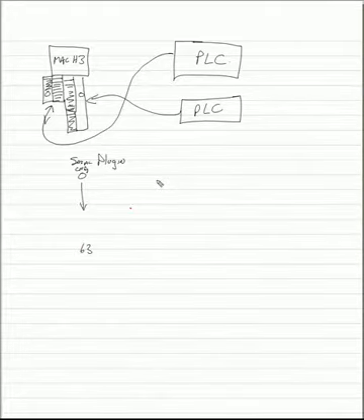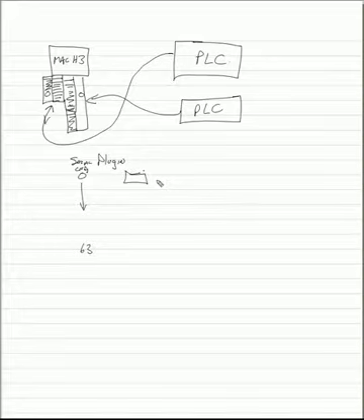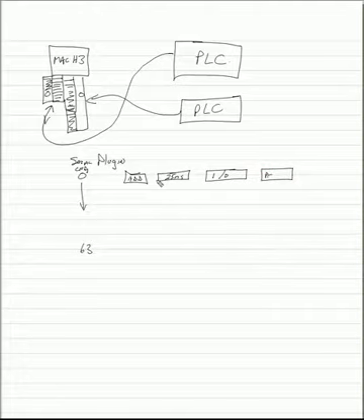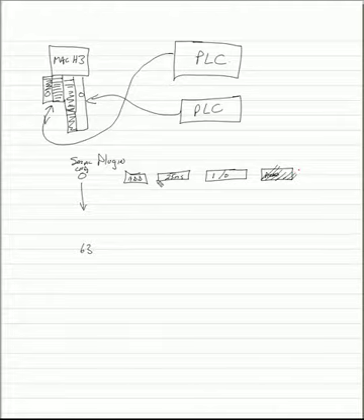So there are 63 of these, and each configuration area is set up with a start address in the PLC to start transferring, a time of refresh, say 25 milliseconds as default, and whether it's an input or an output, plus data for the protocol involved. Most of this data is unimportant to you, and all you'll really be using is the address, the time, and whether it's input or output.